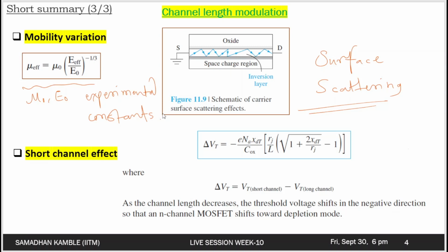We also assumed that the gate area was the same as the active area in the semiconductor, and using this assumption, we have considered only equivalent surface charge densities and neglected any effects on threshold voltages that may occur due to source and drain space charge regions that extend into the active channel region. So this is the effect on threshold voltage because of source and drain space charge regions that we have neglected. This particular delta Vt is shown here, where delta Vt is nothing but the Vt for the short channel minus the Vt for the long channel.